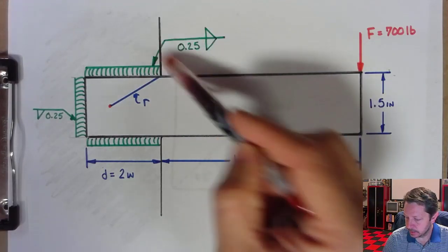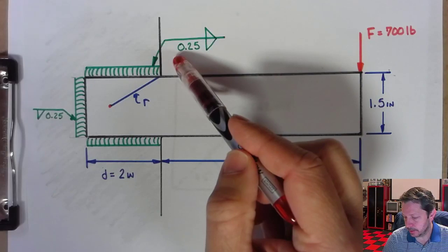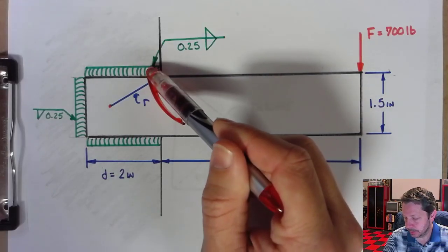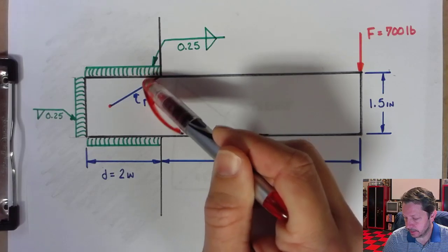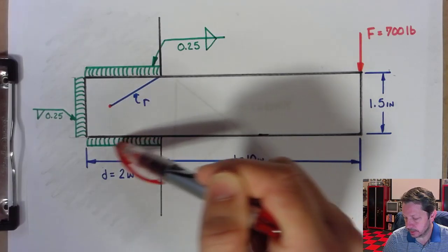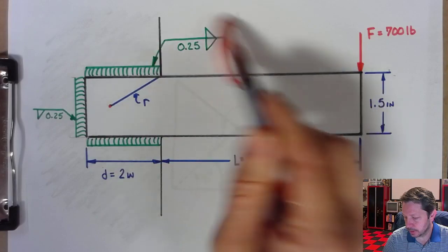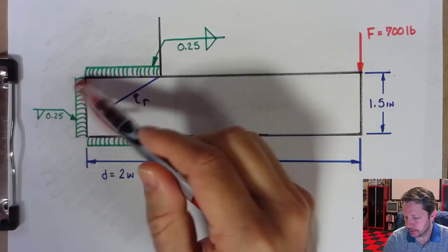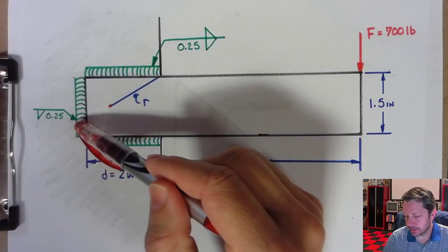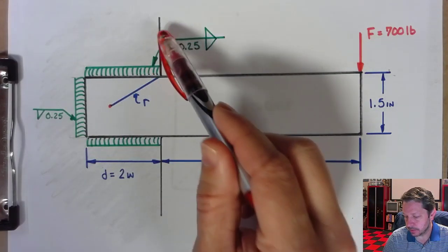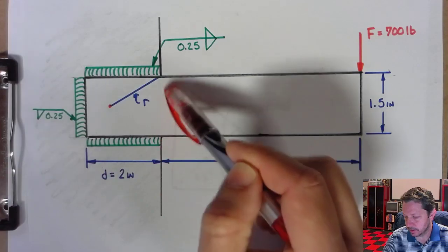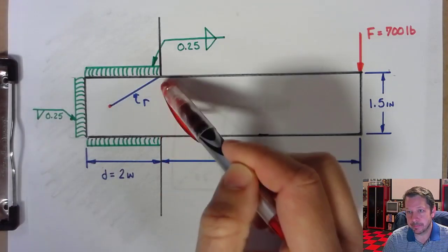But this weld call out is going to give us this weld, the 0.25 fillet on the arrow side, and then the other side of the arrow is this weld. So this one call out gives us this weld and this weld. It doesn't do this one though. This one has its own call out because I couldn't put the circle here doing all around because that would give me a weld back here also, which I didn't want.